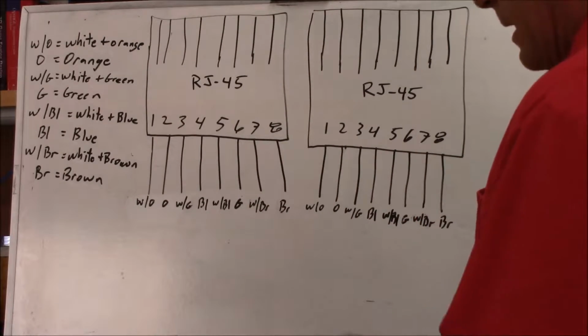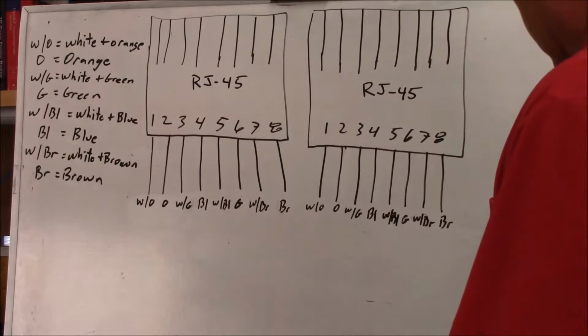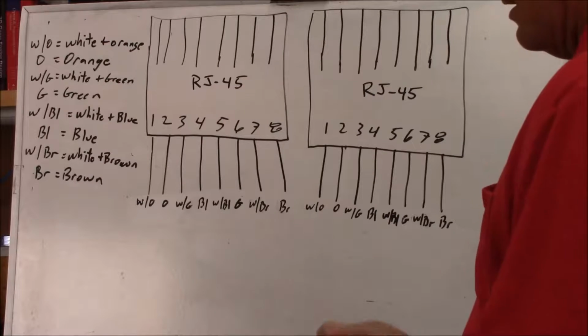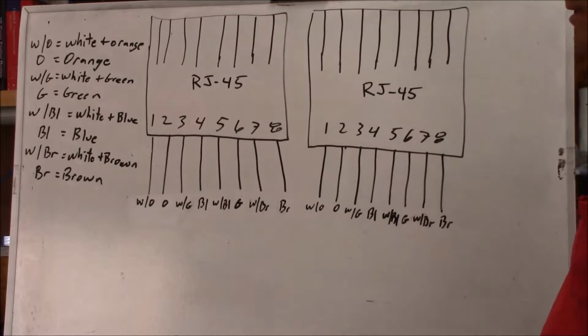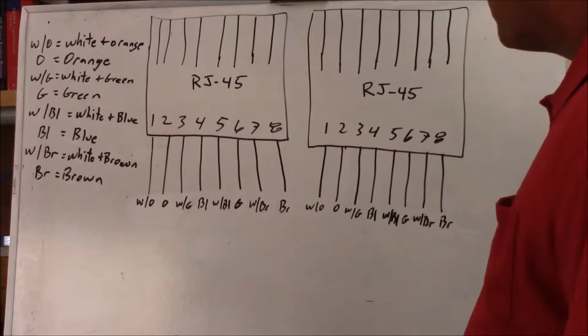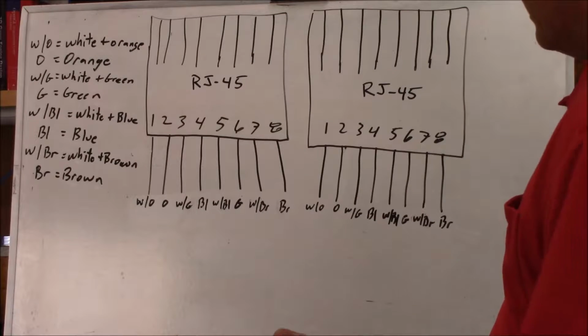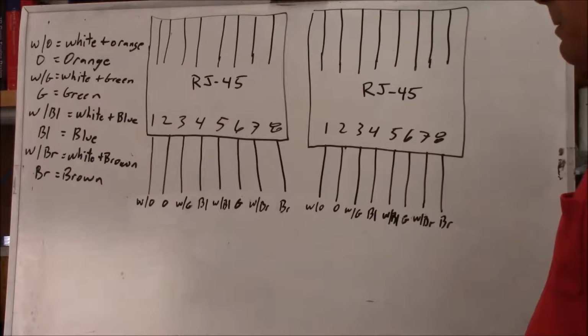And that's also another way. If you're looking at an Ethernet cable in your hand and you see two solid colors right next to each other, you don't even have to know the pinout, because you know something's not right. It's either not an Ethernet cable or it's been made wrong.